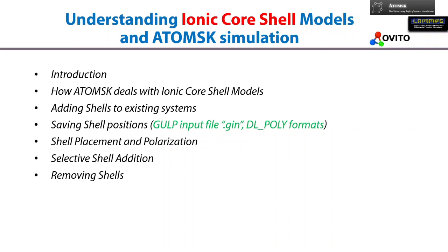You can save this total system after adding the shells in the file format .gin or DL_POLY formats. This is very important because you cannot save the file in the XSF file format, because the XSF file format does not allow you to read those shell positions. Okay, so you will understand this when we go to the demonstration portion.